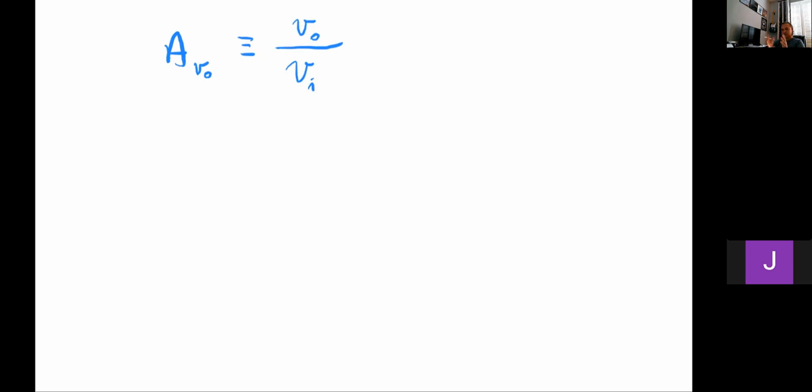It's just a voltage amplifier that is using a biased transistor. It's almost the same, but not really, because it's not truly a common gate, although it is from a small signal perspective. But later on we're going to apply the Cascode idea to what we just finished talking about, which was a single common source followed by a common gate.